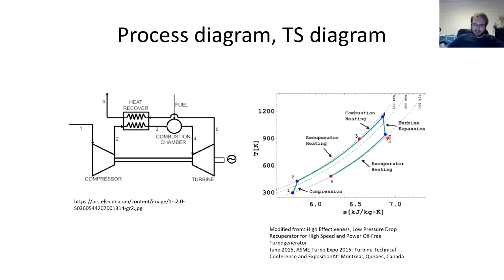And then before the outlet, this still very high temperature heat is transferred in this recuperator, 5 to 6 to 3 to 2. Then at the point 6 there is the outlet of the flue gas from the microturbine system itself, and it can go to a heat recovery heat exchanger for, as I mentioned, for example, heating processes. But you could also have some other thermodynamic cycle getting some extra work, extra electricity.